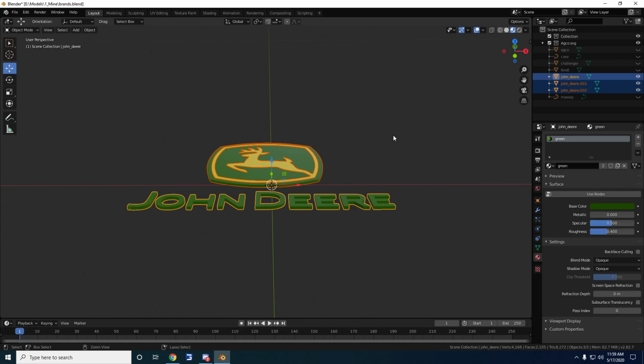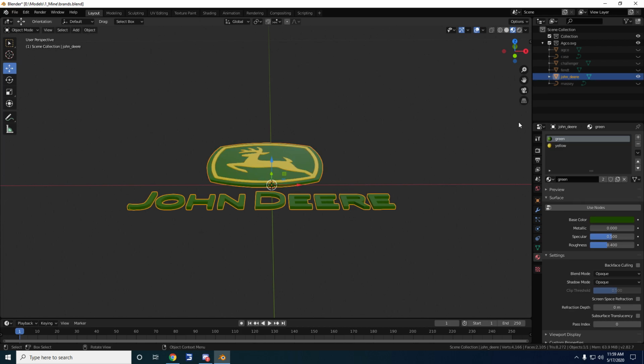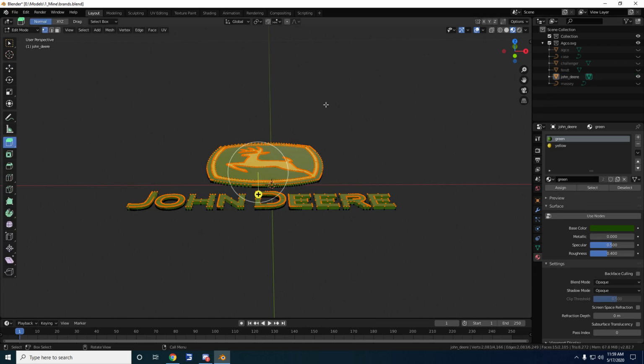Hit Control J. Make sure your cursor is not over here or it won't work. You got to be in object mode, so make sure there ain't nothing clicked. And we'll hit Control J to join them all together.